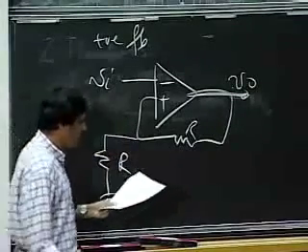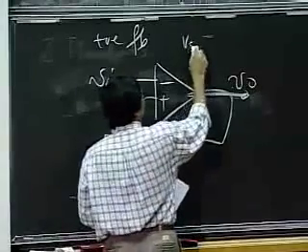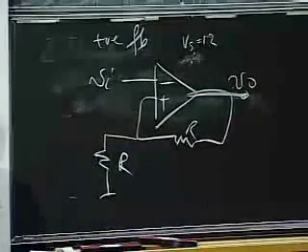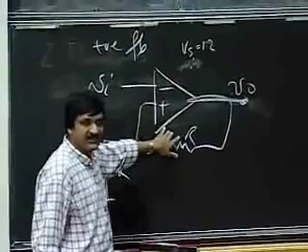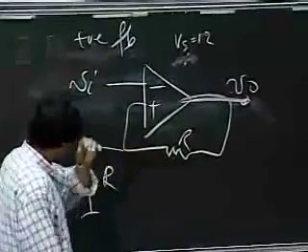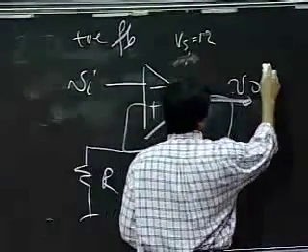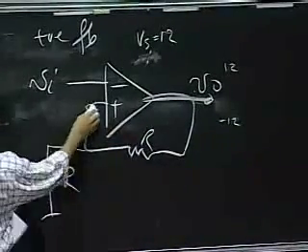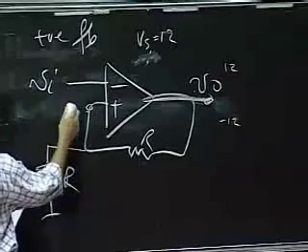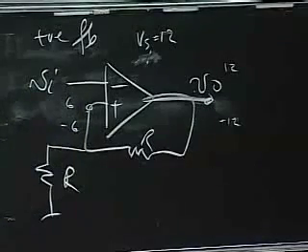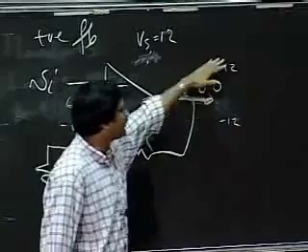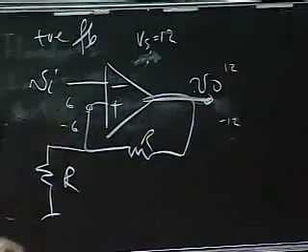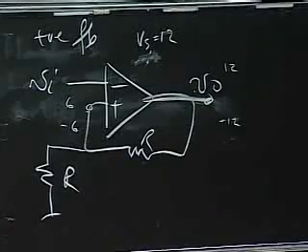This is positive feedback. And in particular, let's assume that Vs equals 12 volts. Okay? And to the negative one, I connect minus Vs. So this guy is going to go between 12 and minus 12. And correspondingly, because these two resistors are equal, this one is going to go between 6 and minus 6. So this is going to be at 12 or minus 12. Remember, the top rail or the bottom rail. And this one is going to be at plus 6 or minus 6.